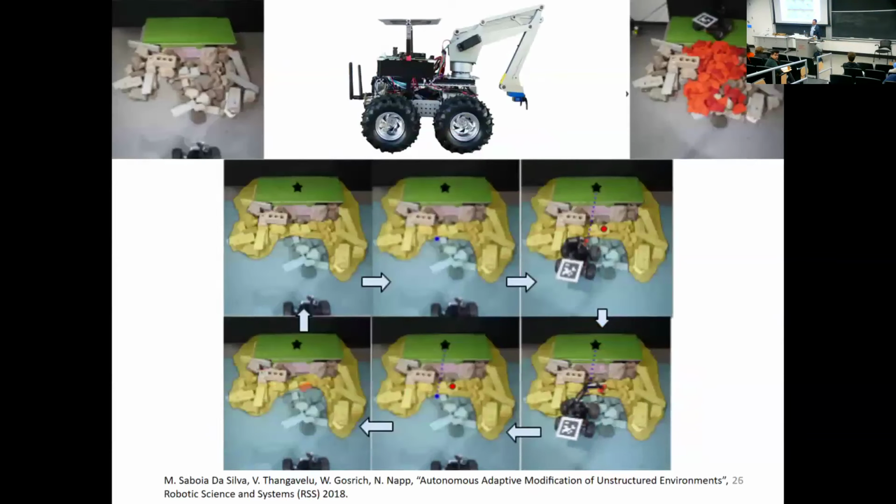Your 2D question. In the 1D world, separating the space of the world that's navigable and non-navigable is very easy, because I just pick a separation point and assume everything behind me is navigable. In 2D, this is a little bit harder. So here, this is a picture of some simulated rubble environment. The blue stuff is navigable. The yellow stuff is not yet navigable. So I can embed this 1D algorithm in this 2D world by the robot trying to make progress to the goal, which is the star, right?